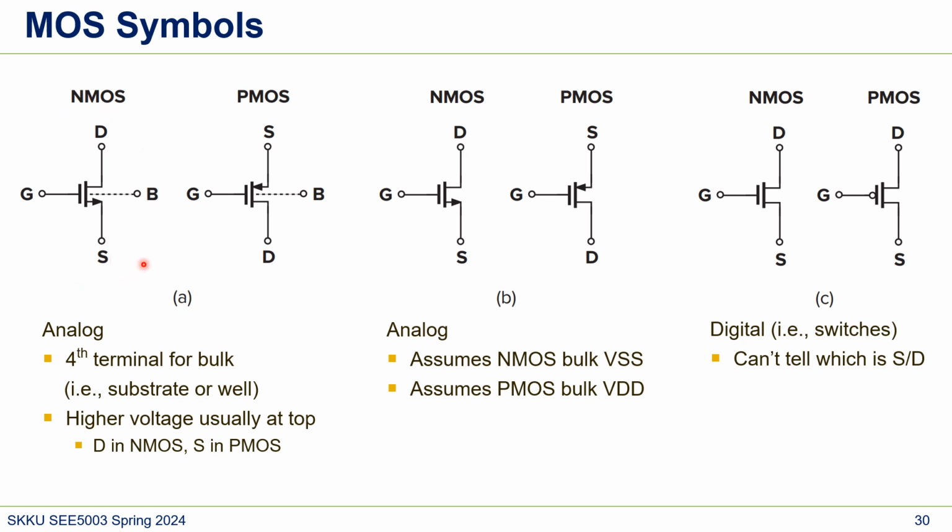So electrons flow from source to drain. But when we define the direction of current, positive polarity is the reference, so the current flows in the opposite direction of the electrons. So current flows from drain to source. And since current flows from higher voltage to lower voltage, and current flows from drain to source in NMOS, the drain has higher voltage. So here, current flows here. This is current I.